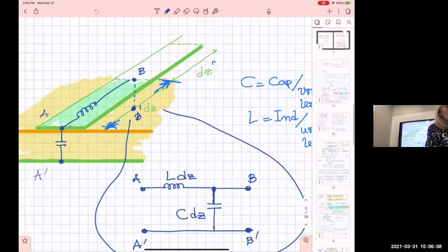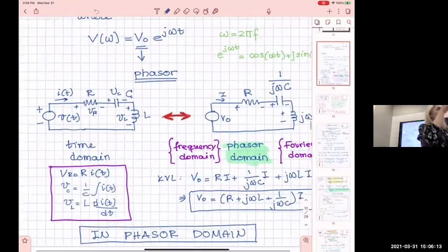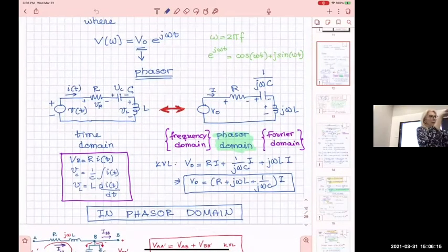Or the conductors could be two strips like this, one next to the other without a ground underneath it, or two strips, one next to the other with a ground underneath it. Even if in reality they don't use the ground, they are two strips like that. Or three strips, two grounds on the side and one strip in the center. Different kinds of things. This is called the coplanar waveguide.